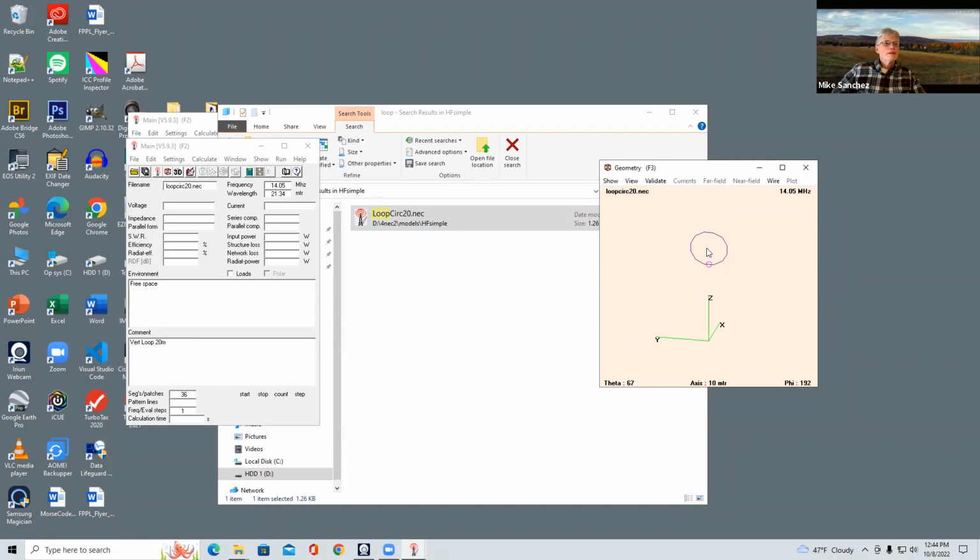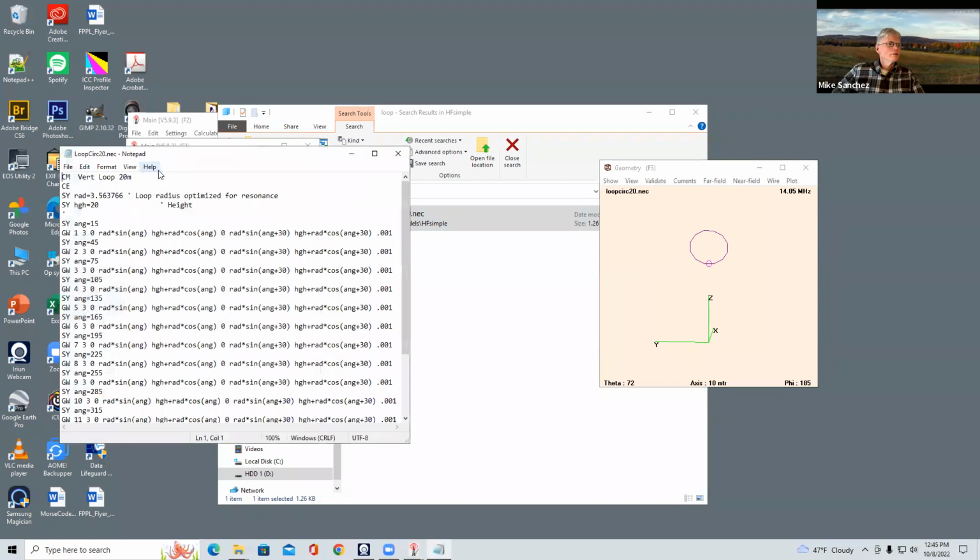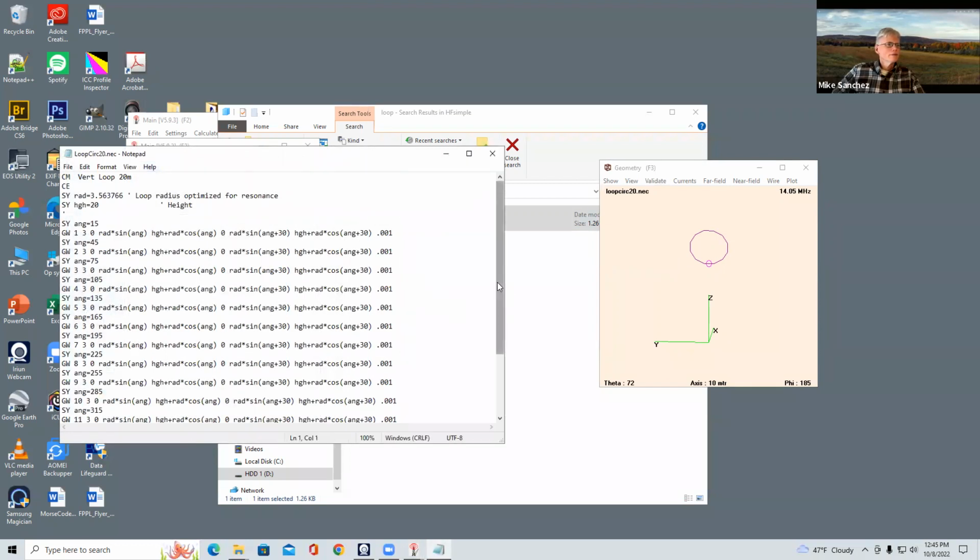The way that you can tell if you're too acute is build the model with your acute angles, run it, and then put little stubs in between that make it less acute and see if you get a profoundly different result, in which case you're too acute. But for a loop, I think it'll be fine. And you can start with this guy right here and just modify it. Which is absolutely the right thing to do. Got a month to try it.